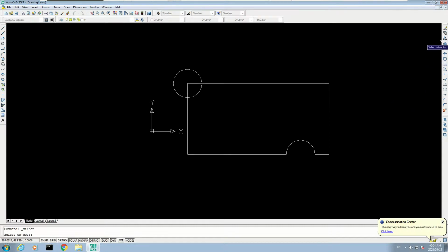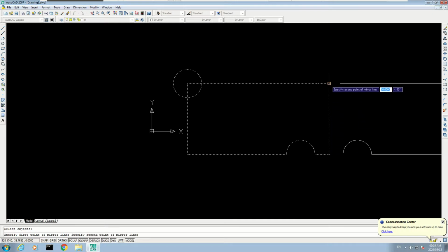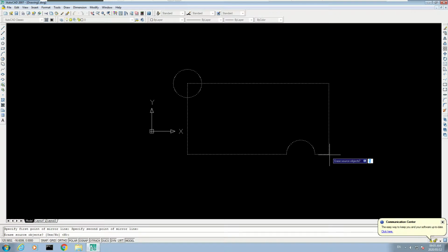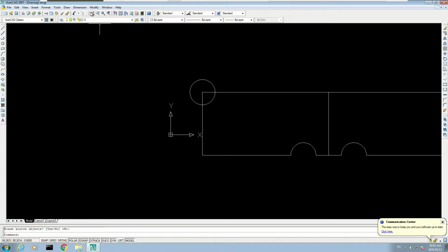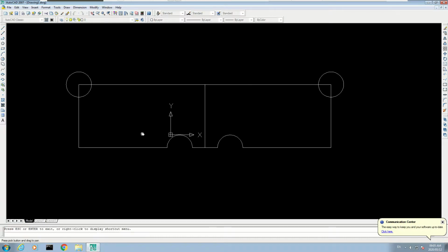Tool from here, this one. If you go one by one, you will see the name. So you just click on mirror, and then it says select the object. So I select the object like this, and after selecting all the objects that I want, I will click enter. After clicking enter, it will ask you to select the point that it will mirror around, or the line. We use a line, for example. So I will select this point, and here select this point, then enter. Then I will see the same object here, identical to the original on the other side.